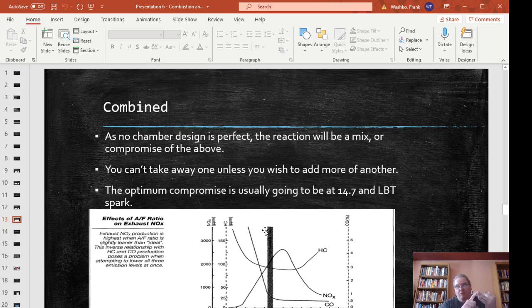We have robust control systems such that the fuel-air ratio is controlled right. We can do CFD around the combustion chamber and the cooling to make sure that the cooling and temperatures across the chamber are relatively uniform. It's all validated through testing to make sure that the cooling is proper and the combustion is relatively complete across the chamber. So most engines these days produce very little emissions.